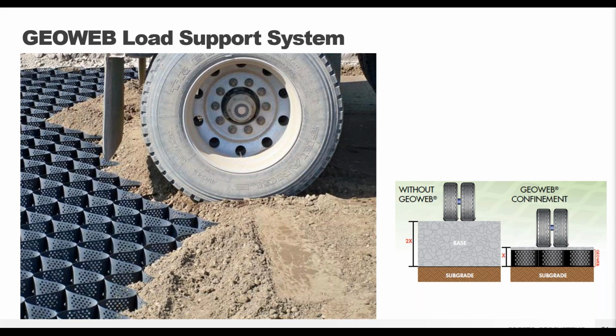So a great benefit to using the GeoWeb system is that you don't actually have to have every cell completely filled in before the road becomes usable. So you can reduce your construction time and materials needed with this approach, all with about half the thickness of your cross-section required by traditional methods to support the same load. So benefits all around.